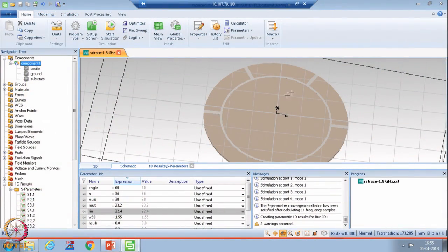If we feed the power from one port, what will be the power at the other ports. Now, just to highlight one more thing, if we give power from port 1 and port 3, by using the same concept, here we should get the sum of these powers and here we should get the difference of these powers. By using the same concept, you can do the simulation. Just to excite these ports, you need to give power here and at this particular port and give the amplitude 0 at the other 2 ports, and you can easily verify the concept of the hybrid coupler.